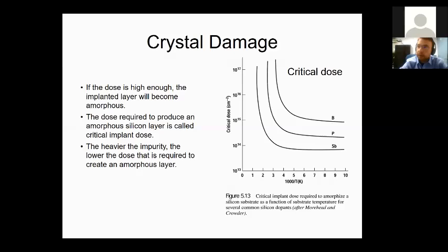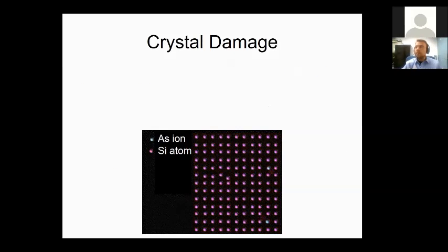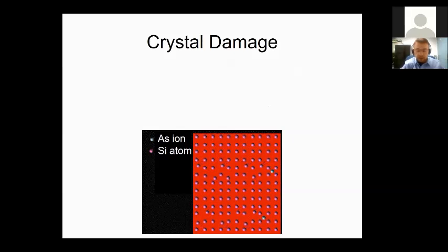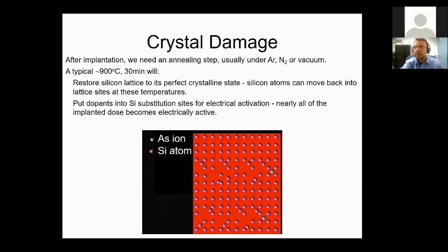So people have to come up with some damage engineering methods. How can we repair this damage? Well, the best way is, again, make use of the diffusion, right? That's what we've seen, how the carriers wander around with the help of diffusion, but likewise, these atoms can also find their locations by heating up, or annealing, I should say, the defective crystal now. And these are the recipes.